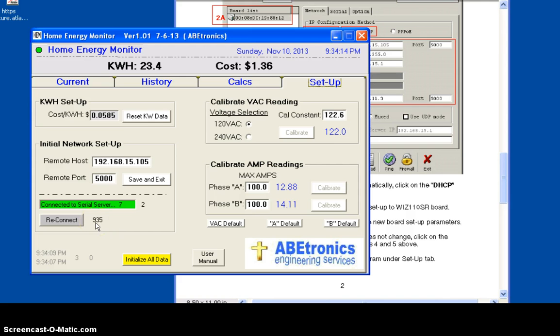This is all the data that's coming in. You can see it goes from 0 to 1000. That's the buffer, so you can see that it's always communicating with the card. Also there is a little indication up here. Yellow and green means it's communicating. That's the update time. If it's ever red, that means it's stopped communicating, and you'll probably have to click on the reconnect button.